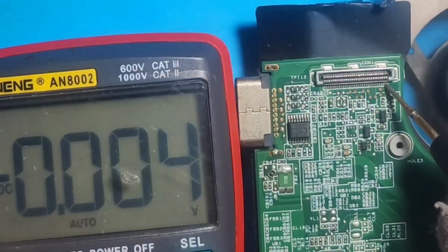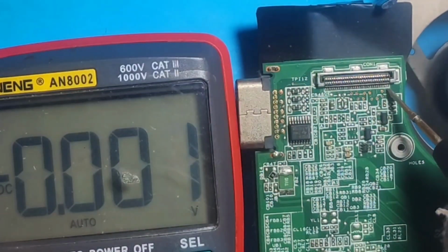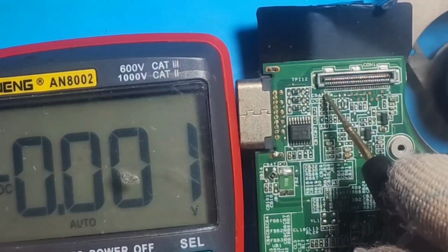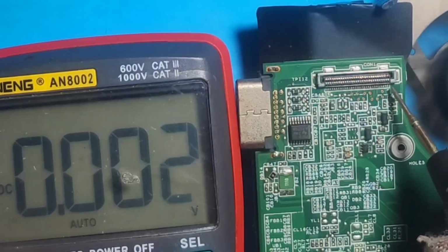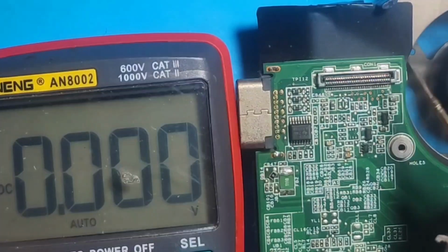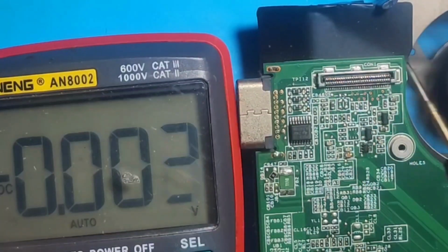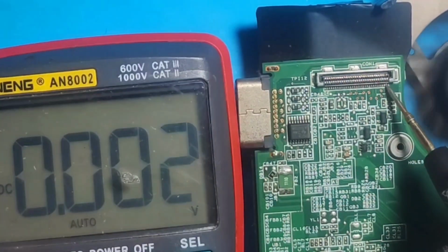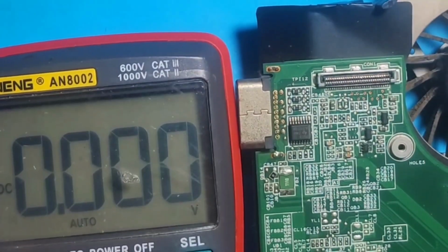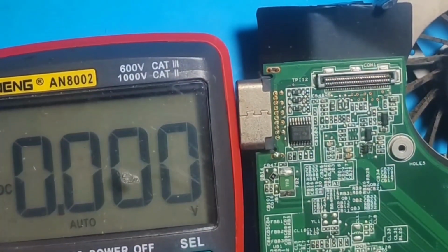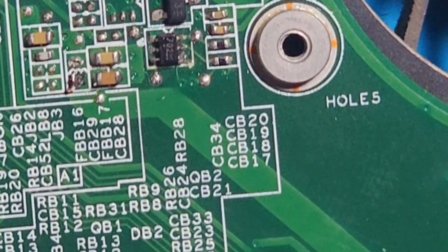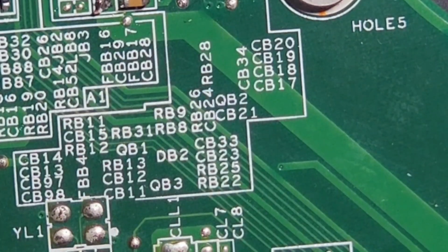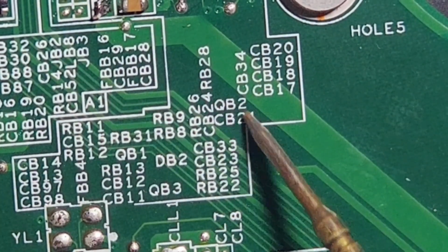So we need to check those circuits that are responsible for providing these voltages. On pin number 30, there's only a coil, but on pin number 1 and 2, the 3.3 volt is supplied from a P-channel MOSFET that is switching the 3.3 volt run power as LCD VCC. So we need to check that MOSFET. Okay, what is the name of the MOSFET? It's QB2. Let me zoom in a little to find the MOSFET. QB2, okay, it's written at this point here. You can see it's QB2.